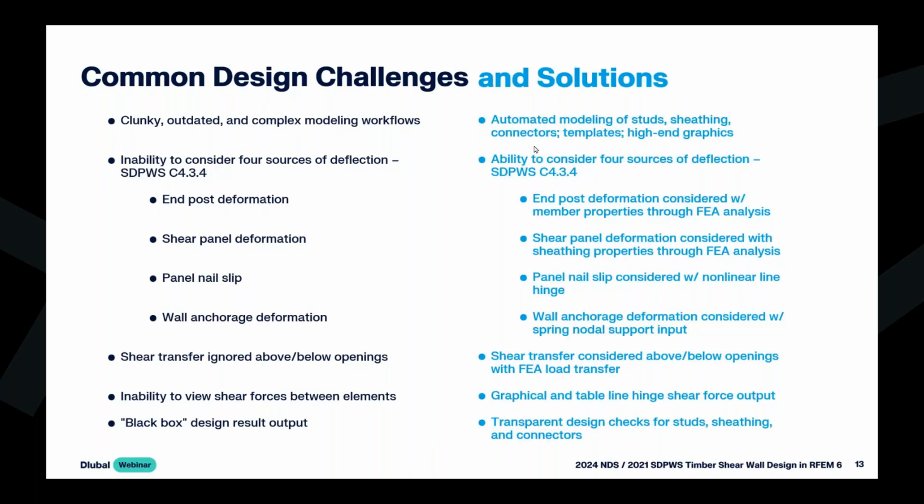And also referring to the SDPWS and those 4 sources of deflection, all of these are considered within RFEM. So the end post deformation, of course, with just general FEA, shear panel deformation. We talked about some of the shear forces that we see from the shear stresses from the analysis. Panel nail slip, we saw this with the nonlinear line hinges that are automatically generated based on the SDPWS code.